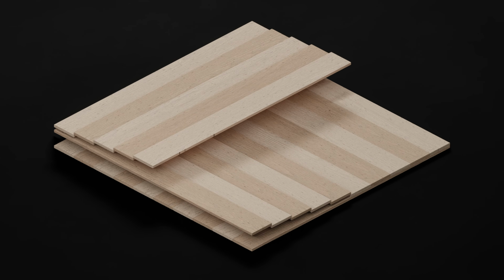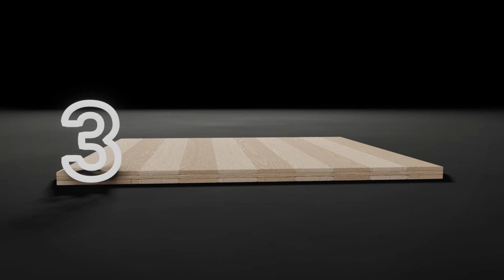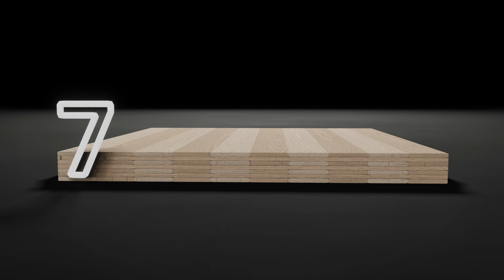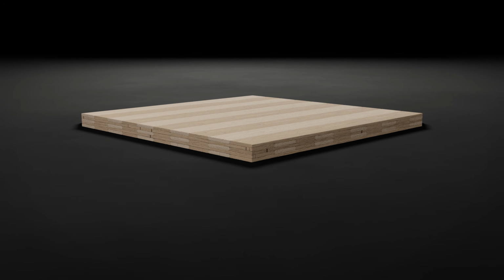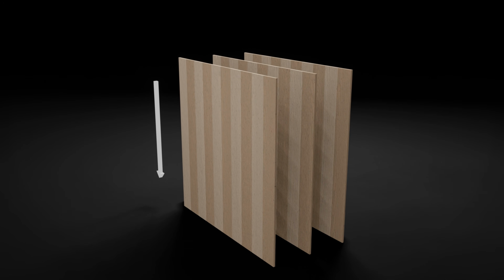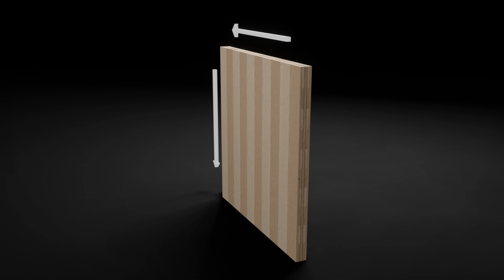Cross Laminated Timber, also known as CLT, is a mass timber product that consists of an uneven amount of layers, often 3, 5, 7 or 9, that are glued together at 90-degree angles from one another. By gluing together layers of wood at perpendicular angles, the panels provide exceptional strength both in vertical and horizontal directions.